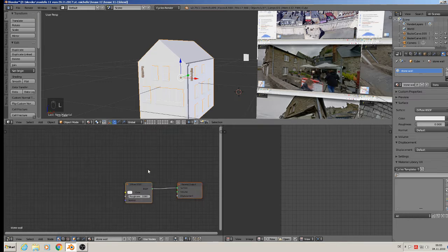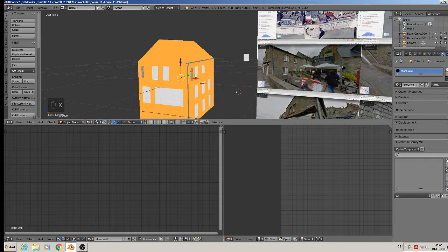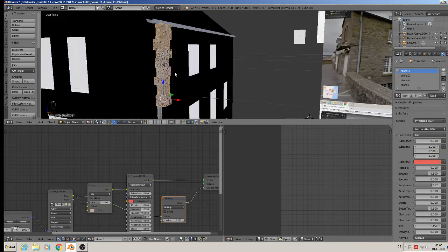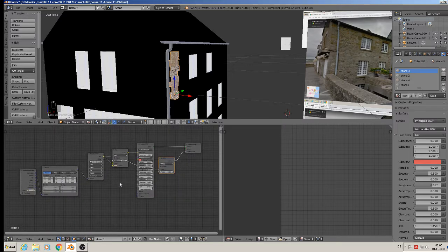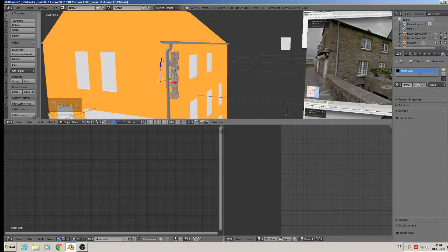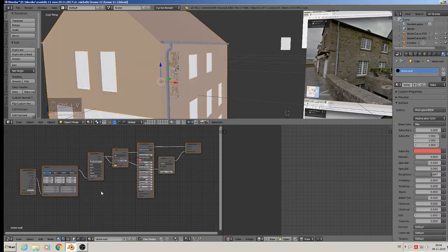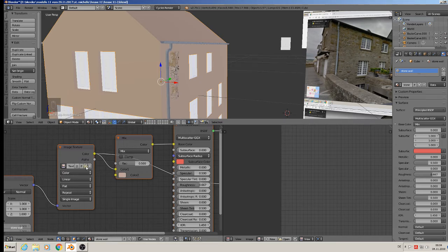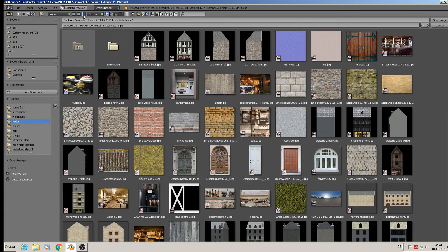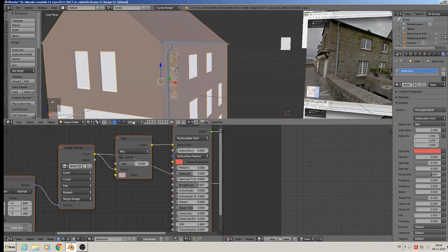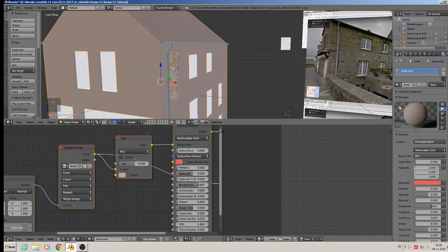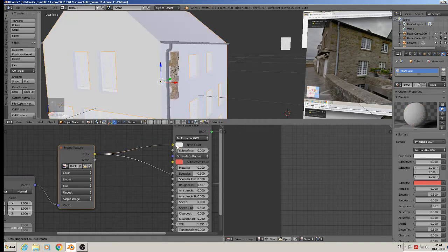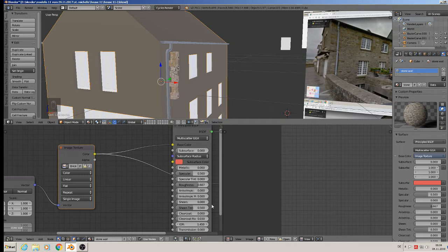Now we have that. We make it simple and delete here all what is in. Then we go to the copied stone material, and here is all done. So we select all, Control C to copy, and then we go to the new node and plug it, Control V input. But we need a stone wall, not this material, so we can take here from the folder, from the texture, our stone wall texture. And why we don't see there some? Because we haven't unwrapped. I delete the mixer because we don't need it, and put it directly into the base color, so we have that there.